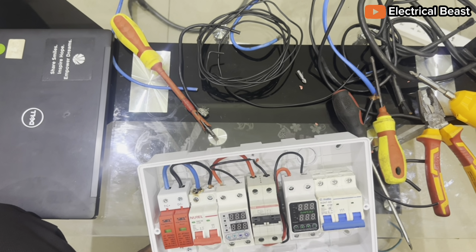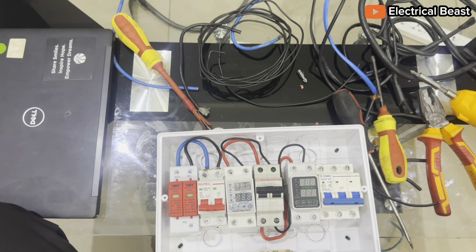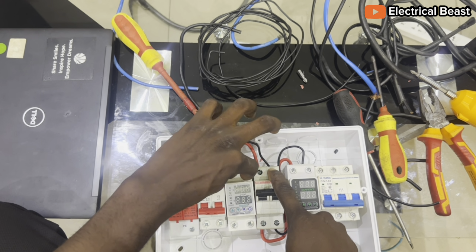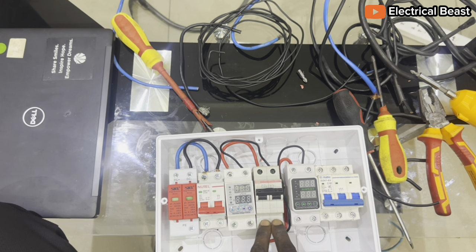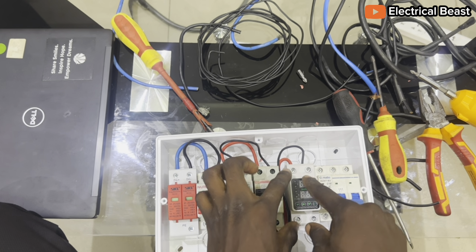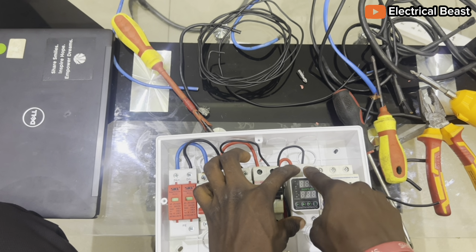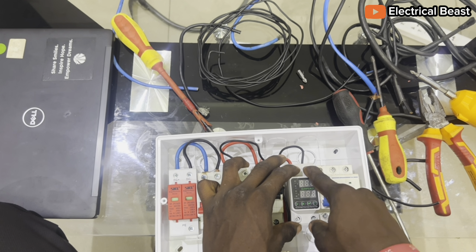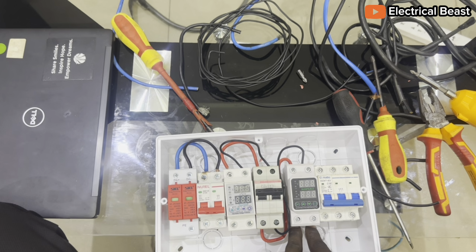Then also you connect the inputs from your grid or your generator up here, then it loops to the AC surge protective device. Then the output from the grid goes to the AVS. Then the AVS checks the current and voltage to make sure they are in the right range. Then it sends the output down to the input of the inverter to protect the inverter from high voltage and high current.